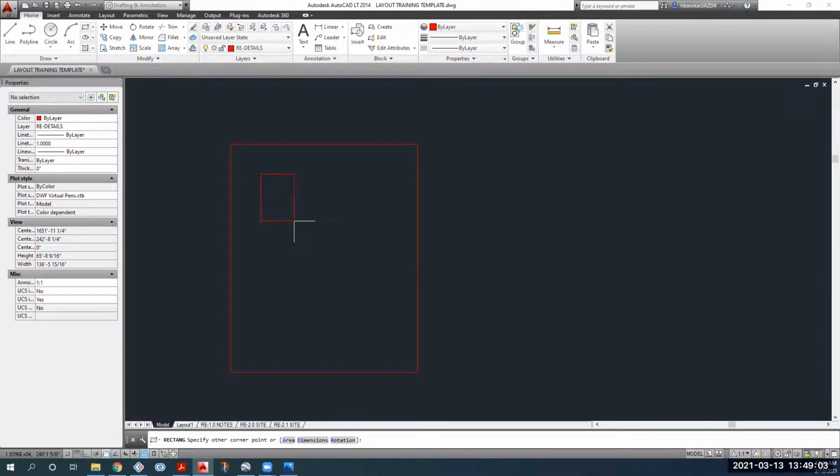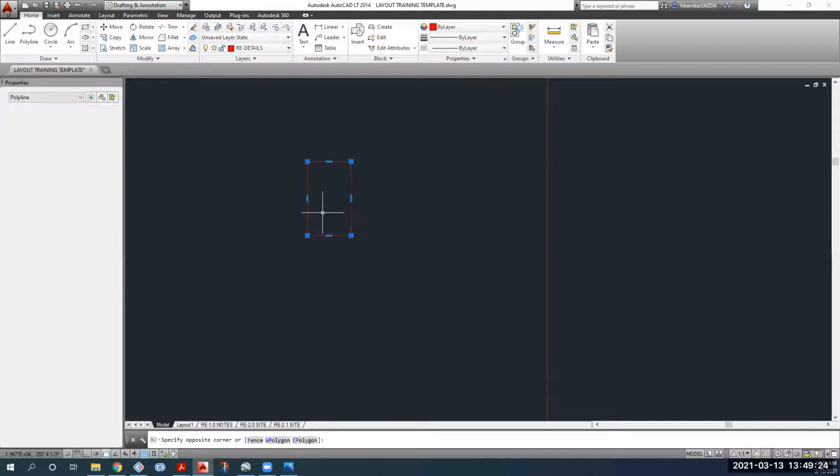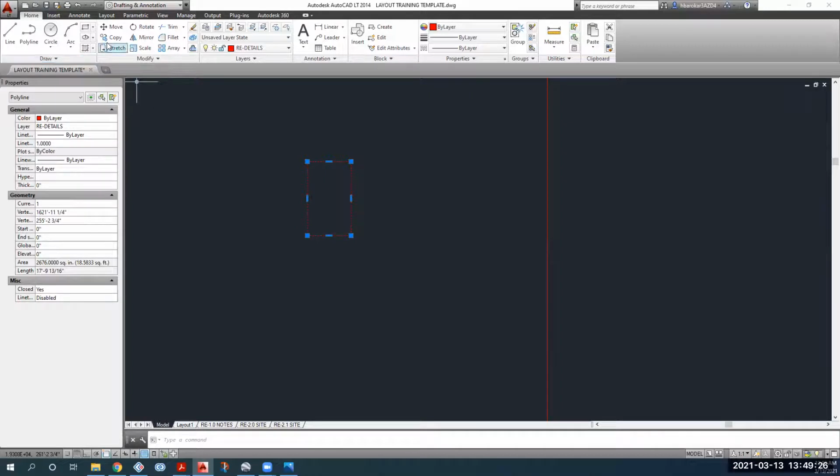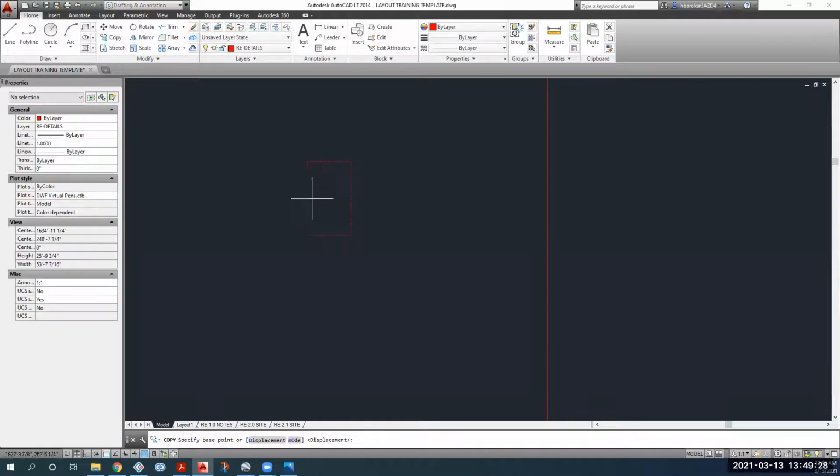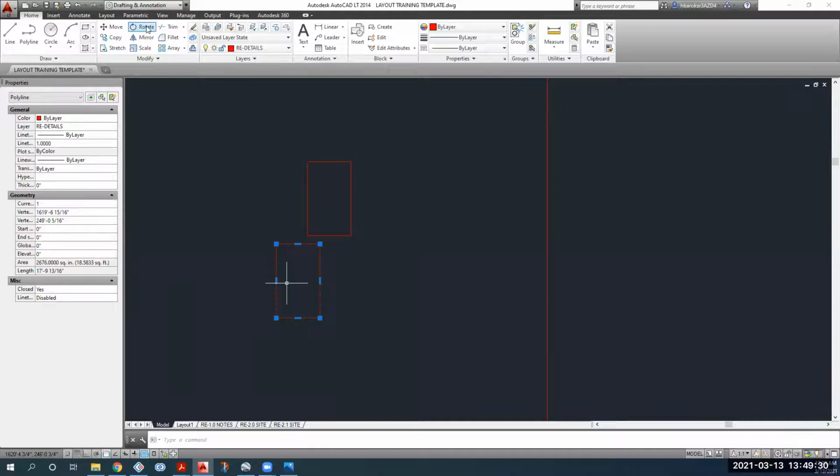So you go to the rectangle tool, click, then you trace, and then you press D, okay, dimensions, and then you enter the two dimensions. So I'll go 40 inches, enter, 66.9 inches, enter, and then this appears, and you have to click again, okay? So this appeared. Now there is another interesting thing. You need to copy this and rotate this to make it into landscape.